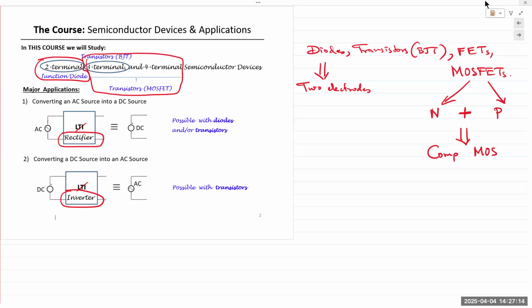Some of those homeowners decide to have battery packs installed, and there's an inverter that goes along with that battery pack. So the battery is DC, receives solar energy, charges up until its capacity is full. The output of that DC battery pack is given to an inverter, and the inverter outputs 110 volts.